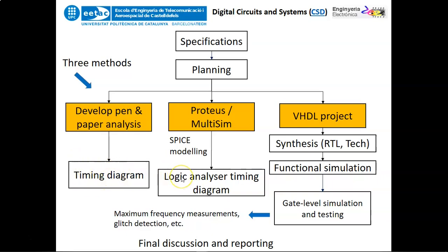Another way, because the circuit is already solved, another very interesting way is to try to mount the circuit as if you were in the lab. This is why you've got SPICE simulators. Every flip-flop is modeled in some way or another, so you can pick up the model of these devices and capture the circuit. As in P1, you captured the circuit and pressed the play button, and then you got what you wanted. In that case it was the truth table, and now it is going to be a timing diagram, for example by means of a logic analyzer instrument. Okay, you have several possibilities here.